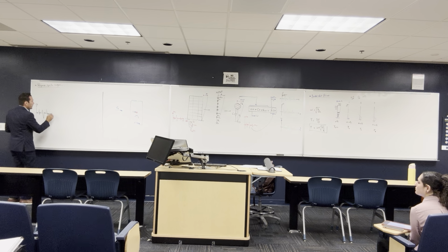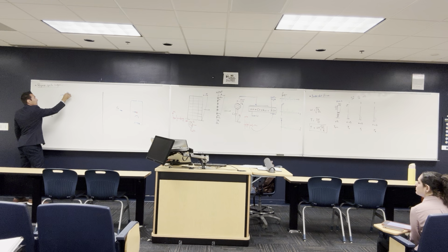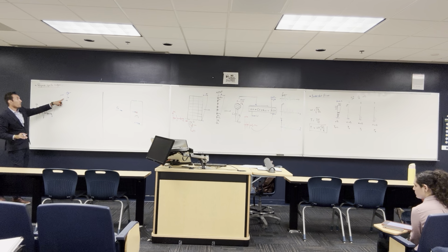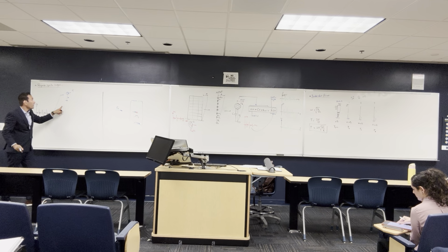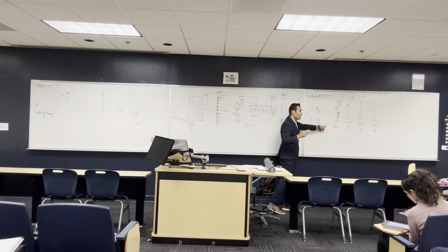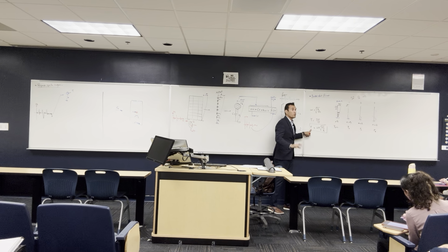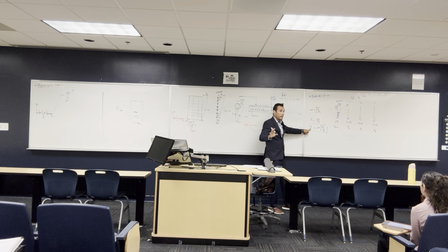They take this earthquake and put it on building number 1. I'm going to represent the building with the same simplifications that we have: mass and stiffness, K and M. By the way, I can represent the building as K and M, or as T, as T1. Why? Because T1 is one variable that is a function of the mass and the stiffness. So rather than saying the building has mass M and K, the building has a variable T equal to T1. If you know M and K, you put them in, multiply by 2 pi, and you get the period.